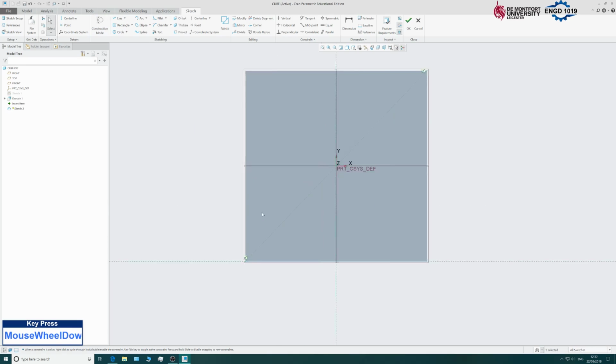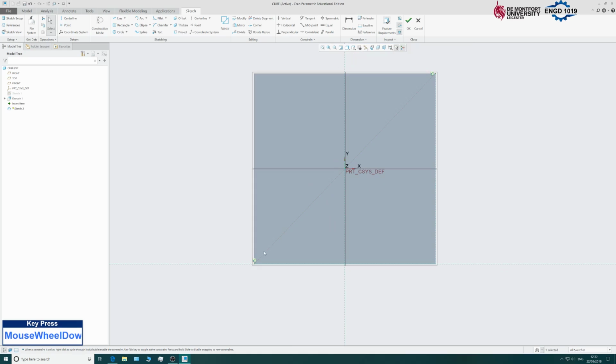Now the idea of using this line is that whatever happens to this shape, I can snap to the center of this line and the hole will always remain in the middle of this face. Okay, so if I go on the circle, click the middle here, click out, and then press the middle mouse button, we can then change the diameter of this to 8.